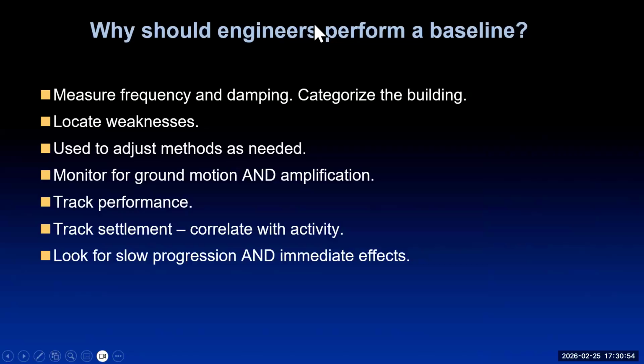So why should engineers perform these sorts of baselines on structures? Well, you want to understand the structural integrity laws and the requirements to make sure that they have enough capacity, and understand if a structure is weak. These are all in the codes. You want to understand if the structure is behaving in a manner consistent with structural integrity, meaning that it distributes forces. And let's say you see an anomaly in a mode shape. You know that you have some sort of structural anomaly in that structure. Now you can do a deeper dive into it.